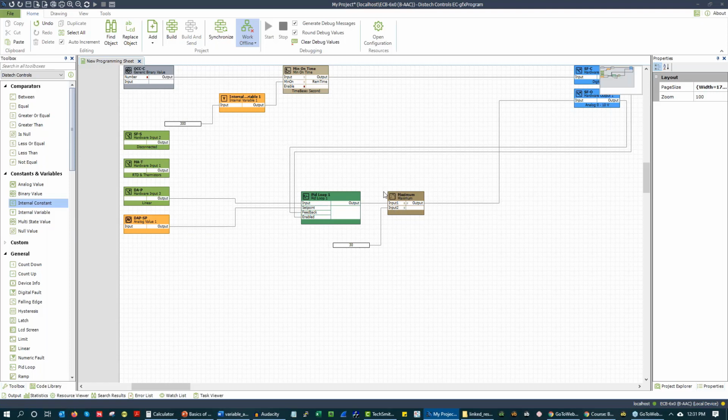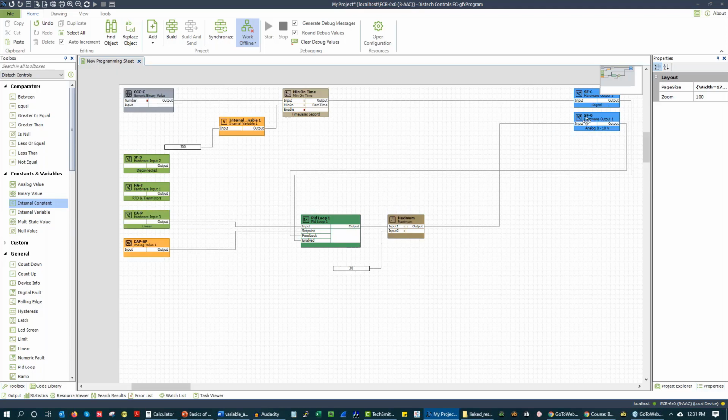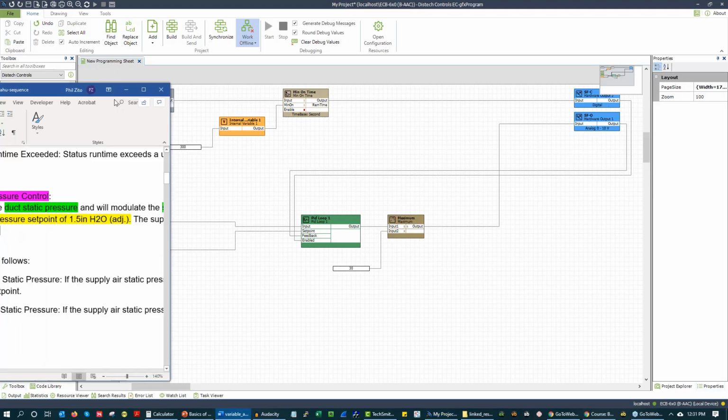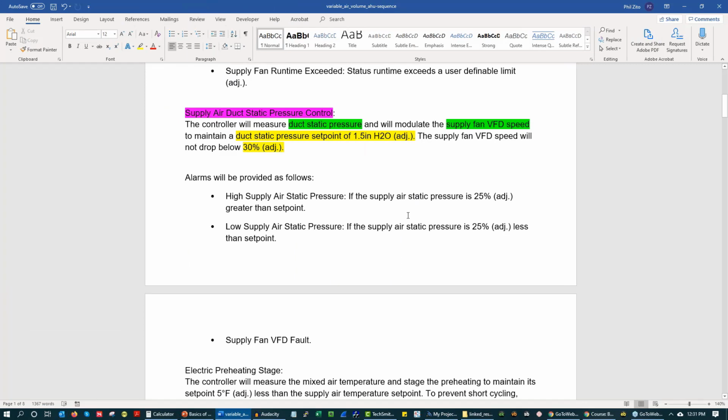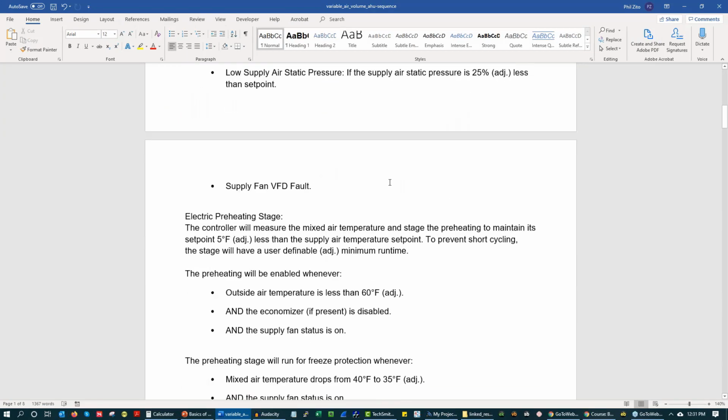And we will use this exact same pattern when we're doing economizer control. So when we're having CO2 reset, where we could reset the damper down, we can use a minimum select object instead of a maximum select. But essentially, we just wrote our supply fan control. Now, granted, we don't have our safeties in here, but we can continue on because we're going to come back to our safeties later. So we're at 12:30 right now, so we've got about 10 more minutes of programming.